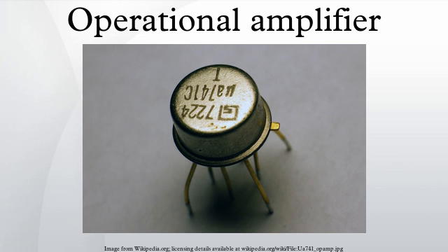Internal circuitry of 741 type op-amp. Sourced by many manufacturers, and in multiple similar products, an example of a bipolar transistor operational amplifier is the 741 integrated circuit, designed by Dave Fullagar at Fairchild Semiconductor after Bob Widlar's LM301 integrated circuit design. In this discussion, we use the parameters of the hybrid-pi model to characterize the small signal, grounded emitter characteristics of a transistor. In this model, the current gain of a transistor is denoted hFE, more commonly called the beta.